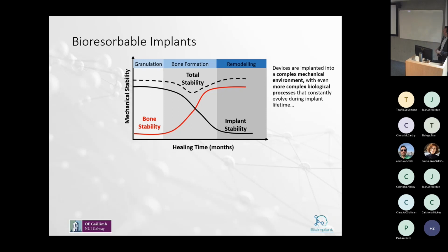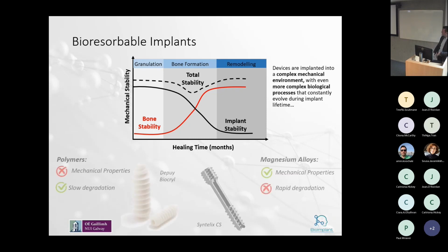But in terms of designing bioresorbable implants, you have distinct challenges because the implant must perform quite a hard load-bearing function at the start of this process. Then in the immediate term, it must degrade in a way that matches the natural healing process of the tissue, and then in the later stages, it has to be completely removed by the body without causing any adverse reactions.